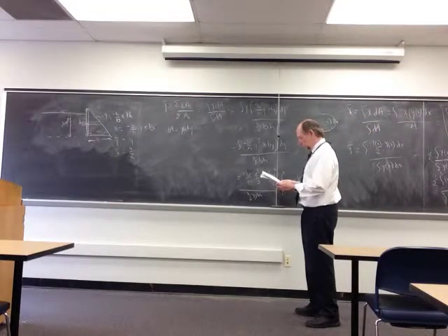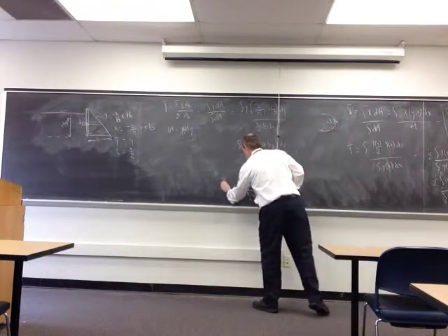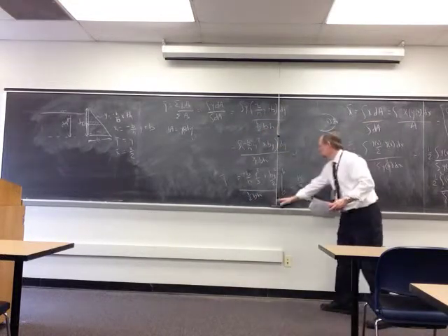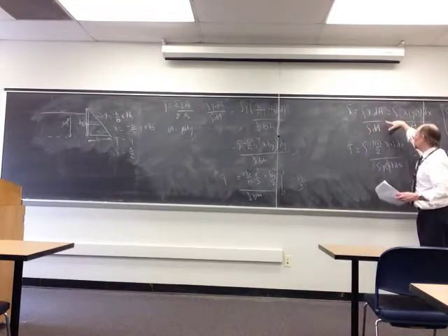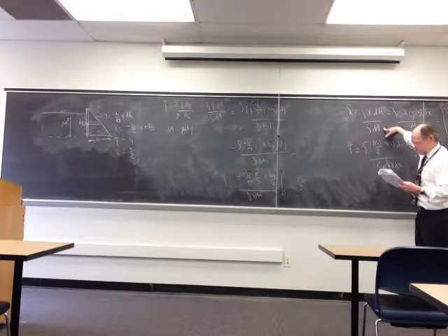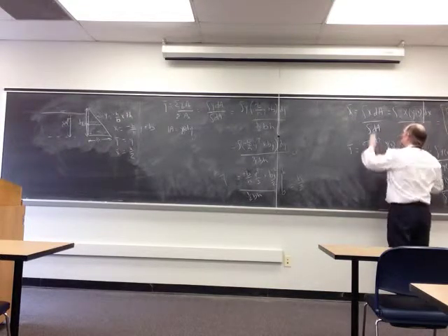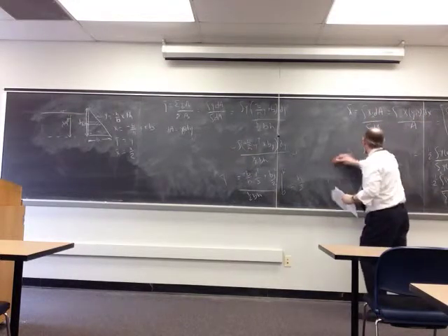All right. So that's the y component of the centroid. The x component of the centroid is still going to be x times dA over dA. But in this case, let's call it x sub i. And we're just going to get rid of all of this.